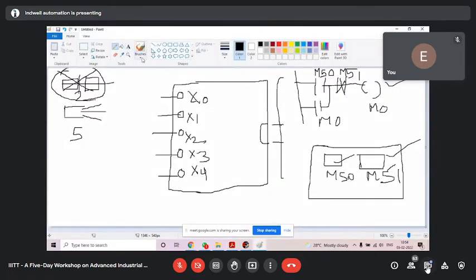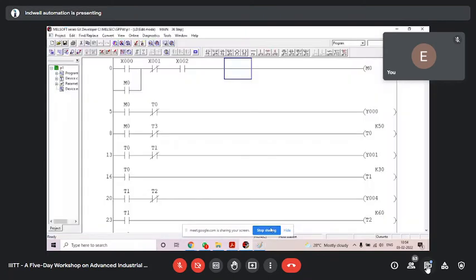Here, see this place. Look at this screen. I am not going to make it M50, M51. First we will do with X0, X1, and then to show you the use of M50, M51, I shall change it further. But first I shall do with X0, X1, because in industry you will have start, stop push buttons, because they don't have the issue of funds and all.